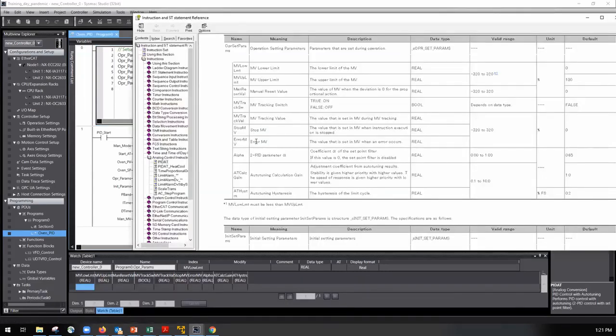Next one we'll look at is error MV. So if there's ever an error in the function block, the input goes beyond the scaling range, or something happens outside of the block that gives a bad value on something, we can actually have this fail to a certain value. This is something that I used to use in the water wastewater world when I was doing integration. On our distribution side of things, you never want your distribution to stop. That means you have to issue a boil water advisory, and it gets messy, paperwork.